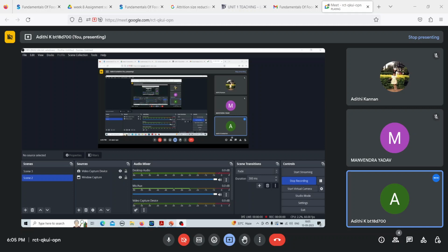M is equal to 100 kg per hour, which I am converting into tons, which is 0.1 ton per hour. 2C or the Bond's constant is given as 3.02 kilowatt hour millimeter to the power half per ton, so I am substituting 3.02. Since all of these are in millimeters, I will be substituting XP and XF also in millimeters to maintain consistency. So XP is 0.1 millimeter, XF is 3 millimeters. Hope this is clear till now. From there I am getting power as 0.78 kilowatts, which is option B.